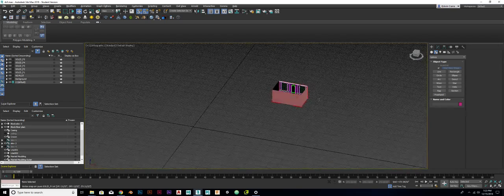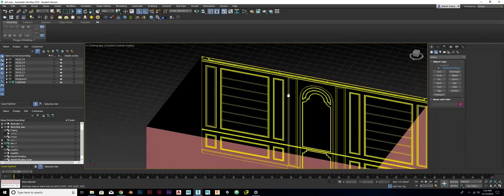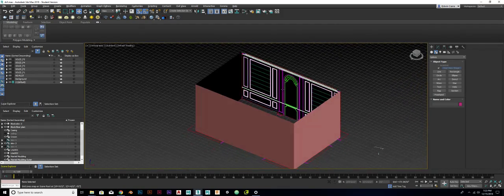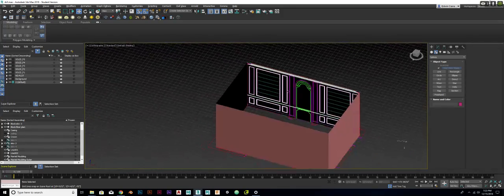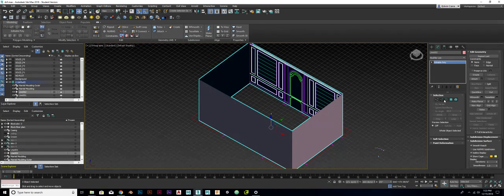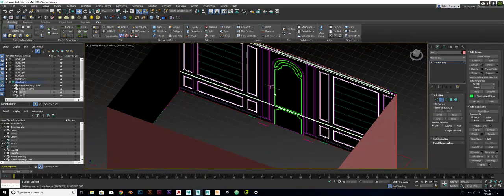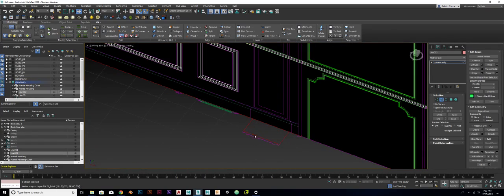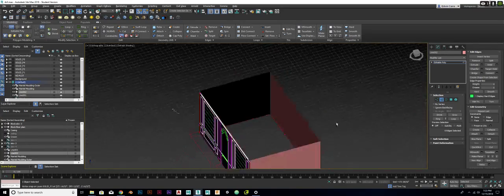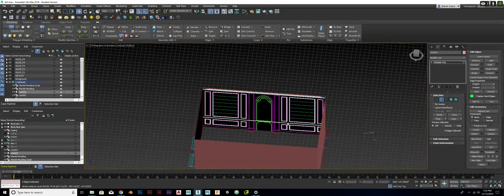It's going to be a little interesting. Just trying to think here exactly how I want to do it. You know what? Let's not do the crown just yet. What I'm actually going to do first is we're going to take our walls and we're going to insert some cuts to be able to make an extrusion and bring out this pillar to the depth that we want it, so that when we do the sweep with a crown, we go all around it in one shot. I think that's the only situation where something bumps out further than the wall. Everything else will be recessed into the wall.